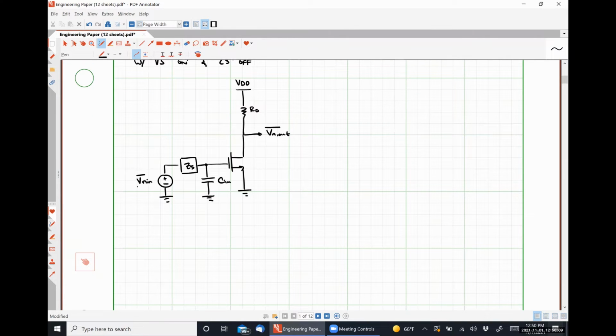I have turned off my current source because I'm applying superposition, and I've just swapped the order of my input noise voltage with that source impedance so that I can see that I have a pretty simple and straightforward voltage divider circuit at the input of this guy, which is going to make it much easier to figure out what the output caused by this input noise is. So if I call this voltage here Vx prime, I can see that